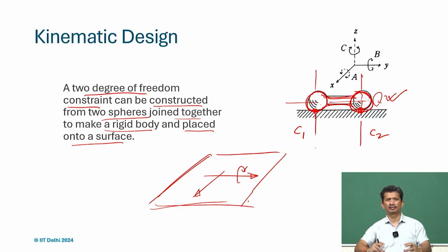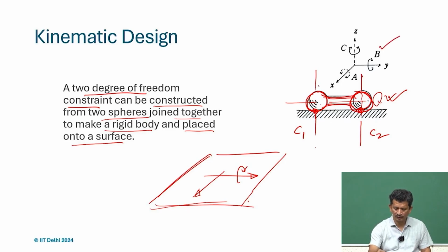So, we just put it there and try to rotate, it can slip at the contact point and can slide and can rotate, or we can do both, it can roll also. So, that degrees of freedom is there. So, x translation achieved, y is also possible. Rotation along y axis, that is b, that is also possible. What about the z rotation?